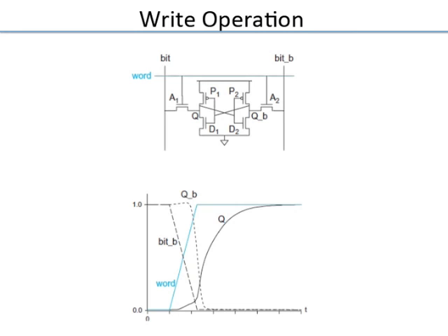So you see, a write happens from the 0 side, where whichever bit line is 0, that one pushes the 0 in. So that is why when you read, you should not have one of the bit lines at 0, because that becomes like the write case, and you will flip the cell.